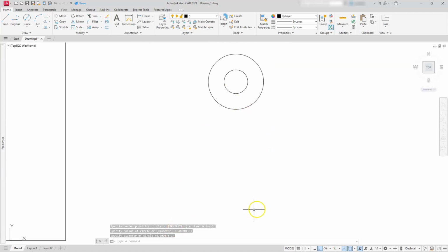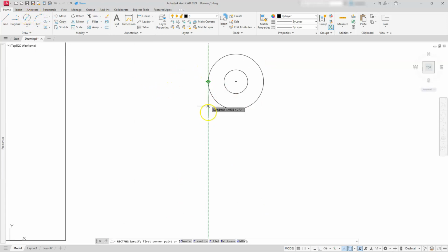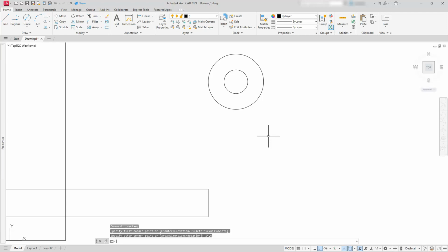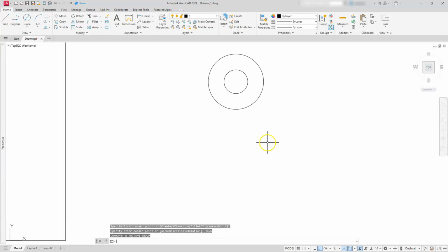I'm going to create the other 2 circles that's underneath here. I'm going to use a rectangle. I'm going to touch, come down here, do a left click here, and then I'm going to type in the coordinates for it. This thing happens to be 6 high, and we know from the diameter going across at the top is 14. All right, so I'm just going to type in 14,6. And I knew it was going to do that. Let me go back to undo. The reason I knew it was going to do that, I just looked down and saw my dynamic input was turned off. Let's put that back on.